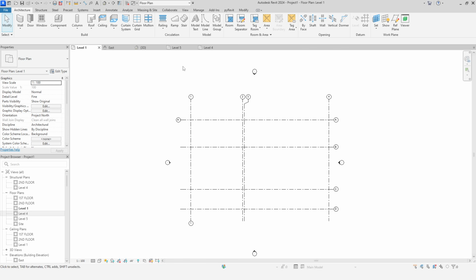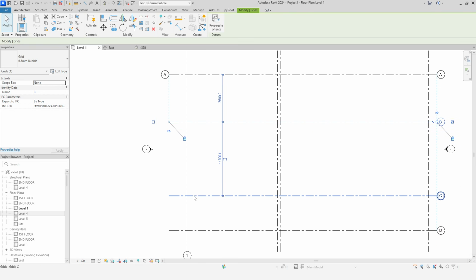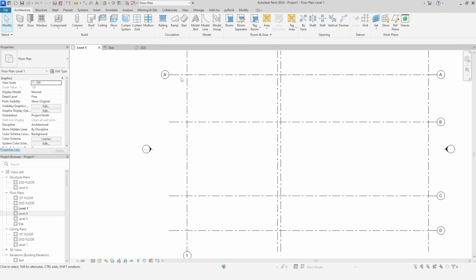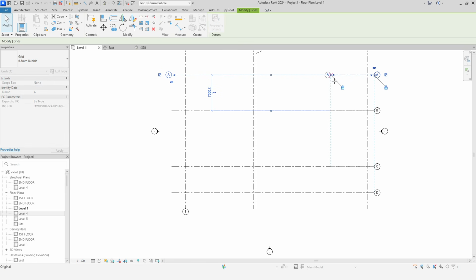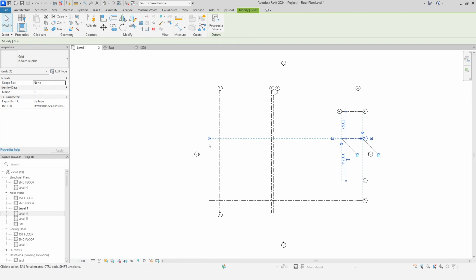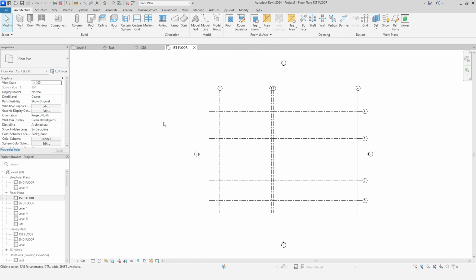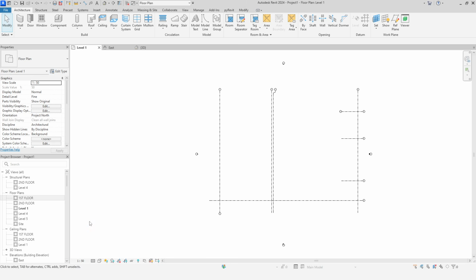Further, here as well we have 3D and 2D extents. We will enable 2D for these 3 grids. We will move the grid starts over here. We can see that the 3D extent marker stayed in the same place while we moved the 2D extents. We see that nothing changed in the other views. Also, just like with levels, the view scale affects the display of grids.